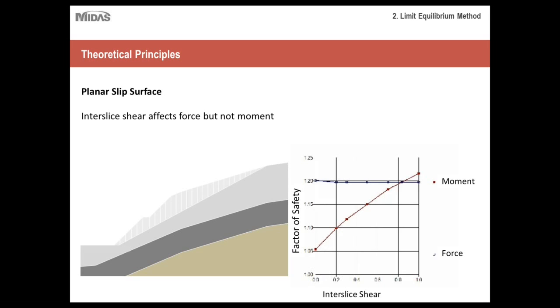So once again, depending on your project conditions, this may or may not be a suitable choice of shape for you. If you're expecting little to no shear forces acting normal to the slope itself, then this may be of use to you. Whereas if you're expecting a significant amount of moment acting on the slope, then that would be another thing to consider, and it would make this shape more effective for you, since it takes moment into account.